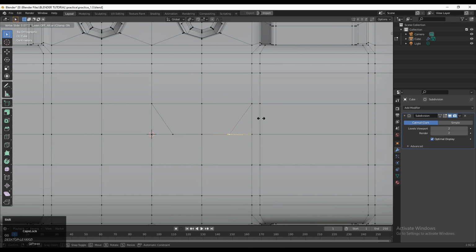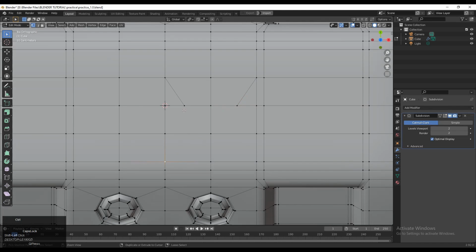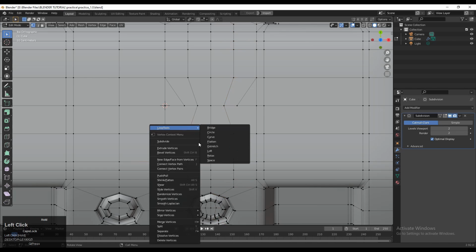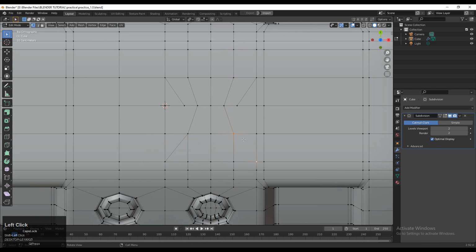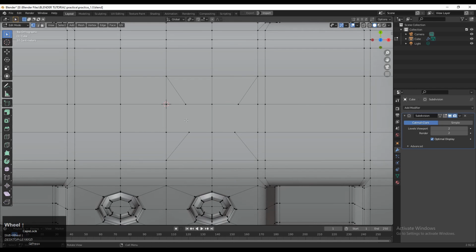Simple, nothing complex. And give the right position for the words. And you can add loop cuts like this. And you can right click and then connect vertex path. Select the words, right click and then connect vertex path. And then you can dissolve these edges. This one way, so you will get the right position for your cuts. So select everything, mesh and then symmetrize.